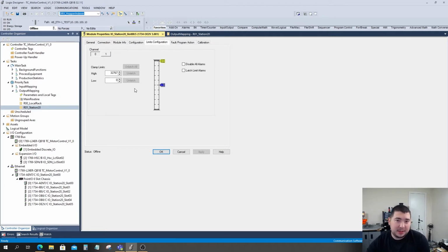For example, if I used smaller motors that operated at 6 volts rather than the 12 volt motors that I use right now, and I change my scaling, it's still going to try to put out 12 volts for whatever my maximum scale is.